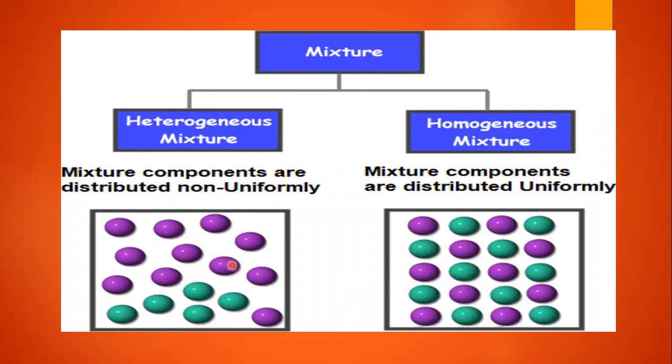But if it is a heterogeneous mixture, they are going to be in parts only, but after some time they will become like this. At the start of the combustion they are not mixed in equal proportions, but they mix after some time, and because of that we have combustion. If they have not mixed properly, there may be no complete combustion. We see the heterogeneous mixture in the case of CI engines, that means compression ignition engines.